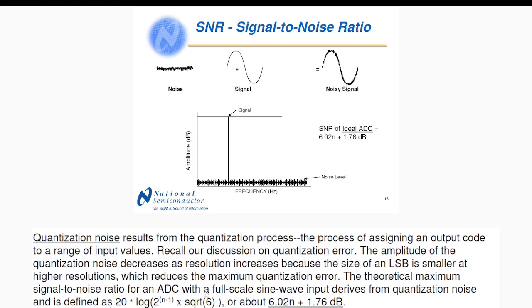That's very much relating to signal processing, but the conversion and mathematics relate to that. I don't expect you to remember this, either this one or that one, but this is the theoretical maximum relating to ADC conversion noise, quantization noise, 6.02 N plus 1.76 dB. Okay.